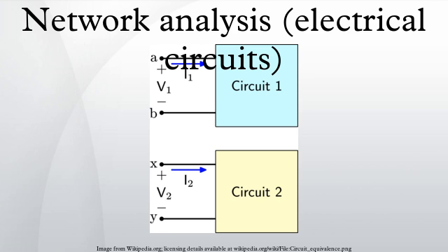Nonlinear networks. Most electronic designs are, in reality, nonlinear. There is very little that does not include some semiconductor devices. These are invariably nonlinear. The transfer function of an ideal semiconductor p-n junction is given by the very nonlinear relationship, where I and V are the instantaneous current and voltage. I0 is an arbitrary parameter called the reverse leakage current whose value depends on the construction of the device. Vt is a parameter proportional to temperature called the thermal voltage and equal to about 25 mV at room temperature.